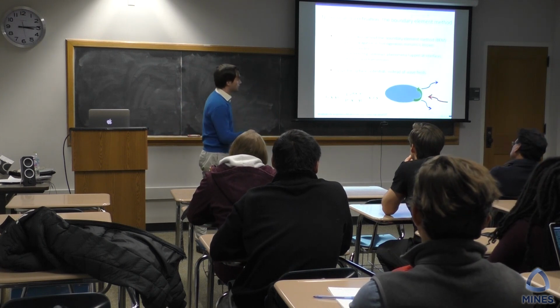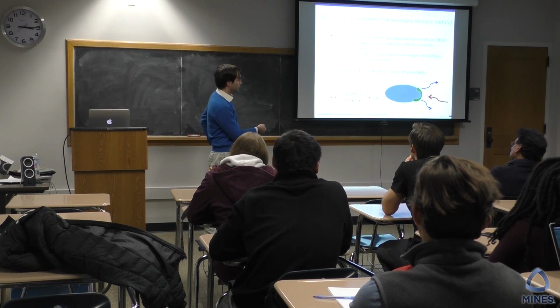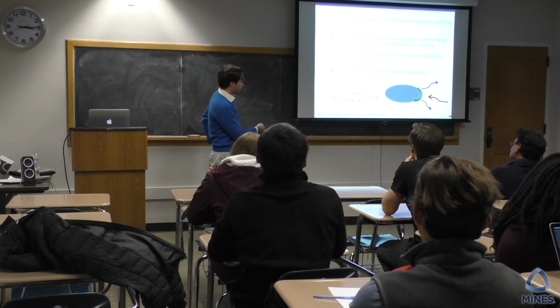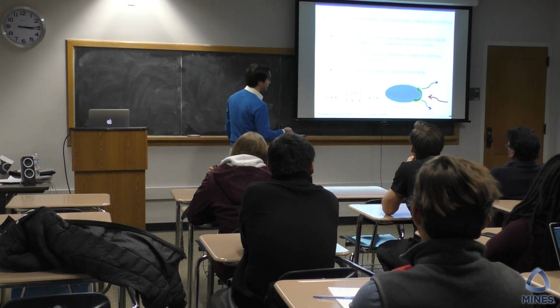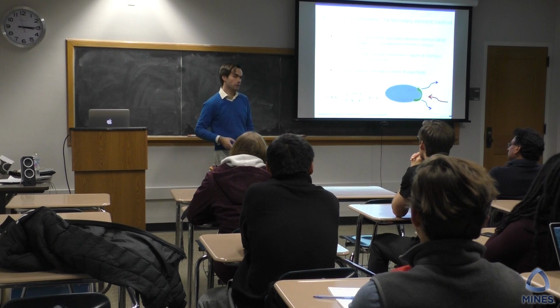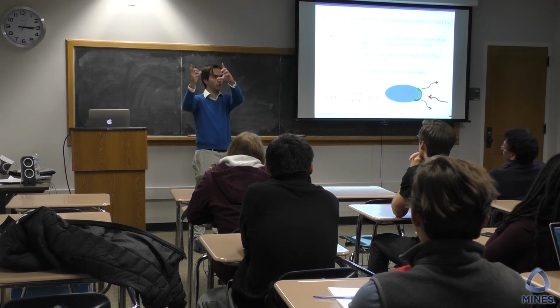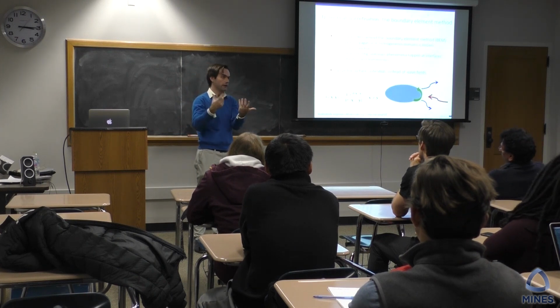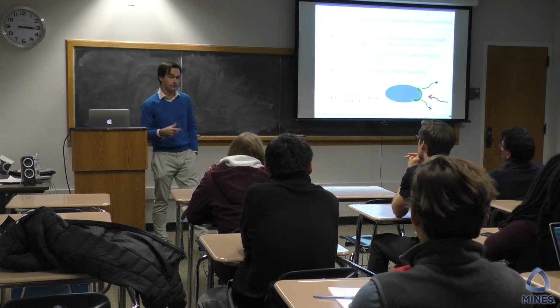So that's the idea. We plug in the Green's function. The Green's function is basically saying that in a homogeneous medium, the wave number does not change, the direction does not change. The only thing that changes is that the amplitude is 1 over the distance between source and observer. So we put this in our model. Instead of using a discretization technique for the fields, we reduce everything with the Green's formulas to the boundary, or the interface of our object. So we reformulate the Helmholtz equation in the volume to a boundary equation at the surface of the object. That's the whole point of the boundary element method, because the scattering at interfaces is the interesting part.